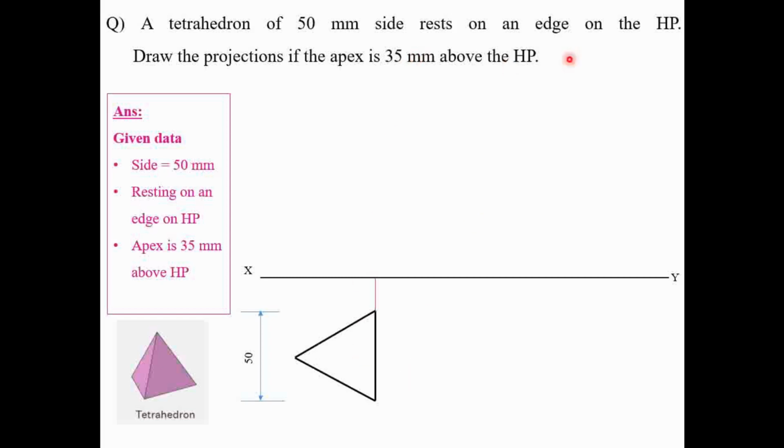and the respective resting edge has to be represented towards the right side of the diagram or in the first diagram. So this is the resting edge, you will find it in the third diagram. Then this tetrahedron has the inclined edges. Then we have to represent those inclined edges by representing the angle bisector. Okay, so the intersection of these three lines is nothing but the actual position of the apex point.